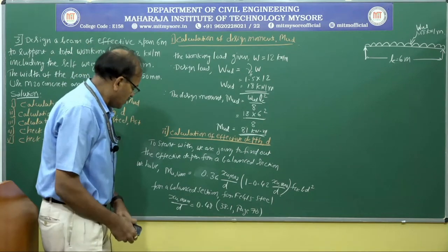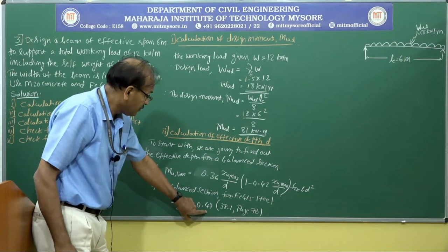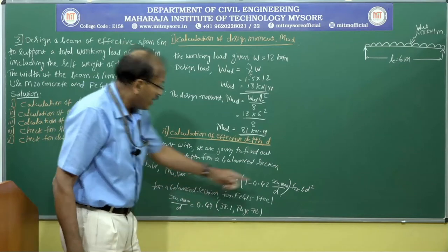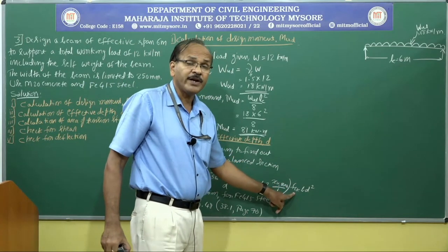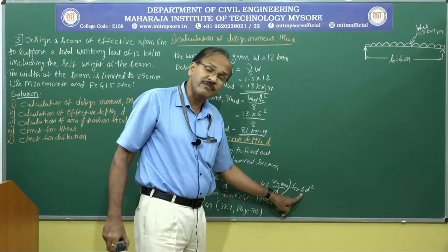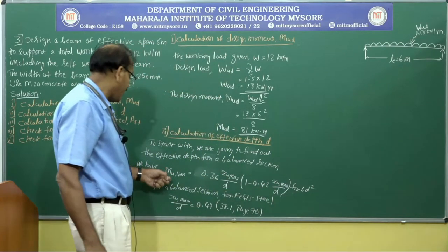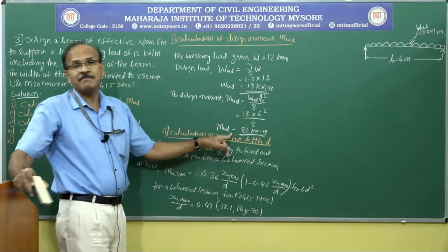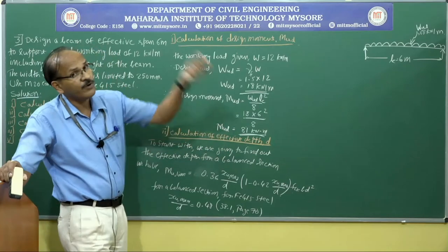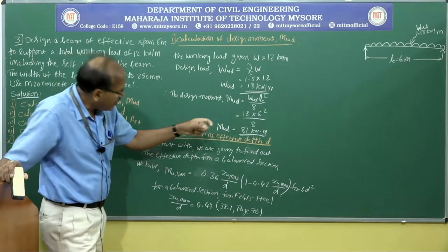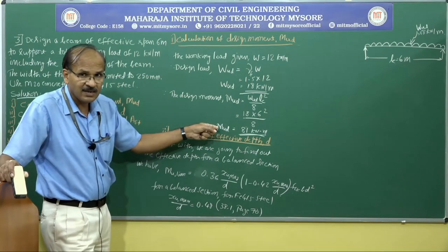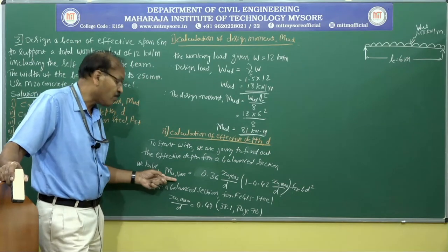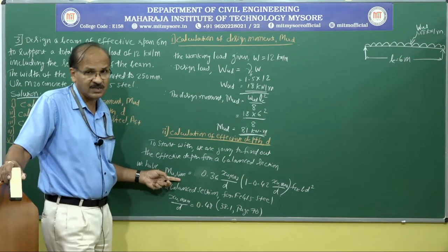Okay. So this value is substituted here, and FCK, of course, for M20 concrete it is 20, B is 250, and for MU limit I am going to substitute the value of MUD. This is the design moment due to external load, and I am equating this moment to the limiting moment of the section, that is the moment of resistance of the section.